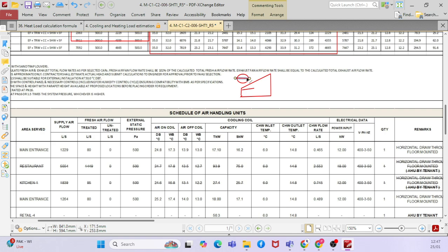So when you apply this in the plot, you will find one inclined line like this through this semicircle. It's not a circle; it is a semicircle. Based on your sensible heat ratio, if you match the value, you will get an inclined line. That line will intersect one reading, and that reading is nothing but your off coil temperature. Clear? Yes, sir.